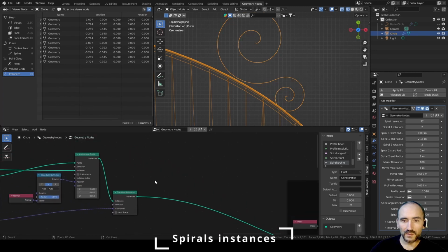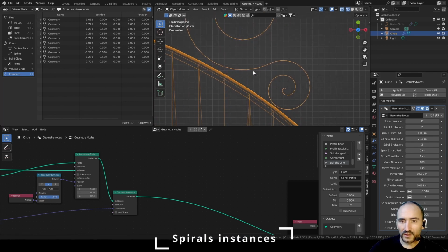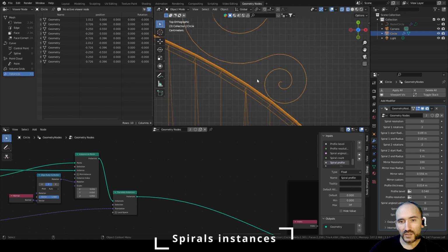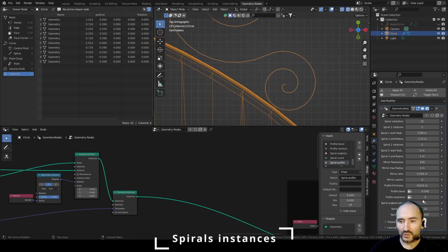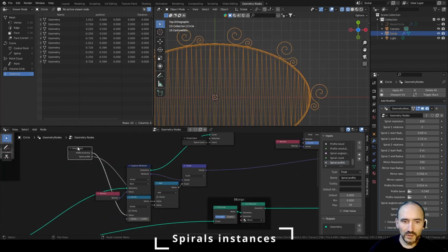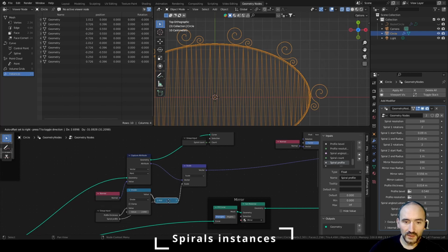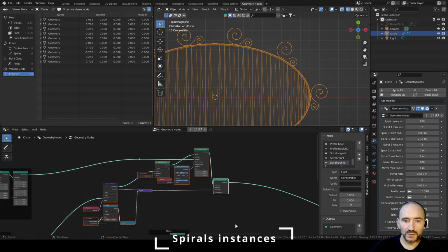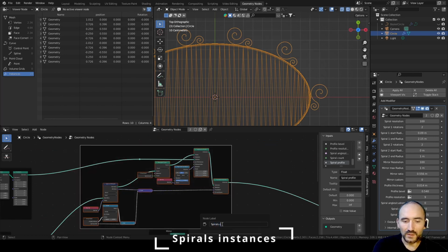and you can see the little difference of these shapes. So I cut these, I set a little value of the spiral. You can see the little issue described before about the rotation and the alignment between the shapes. So I suggest you increase the resolution of the spiral, 100 for example. Next we will add a profile curve on the spirals. Ctrl H these, move all these nodes a little bit up, select all these nodes, Ctrl J, F2, spirals on mirror.